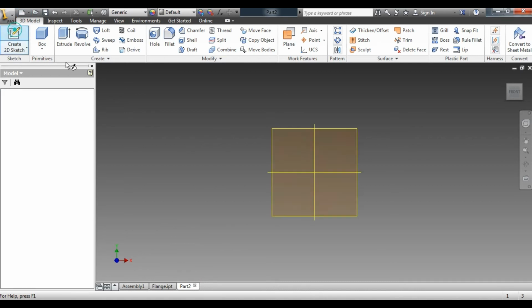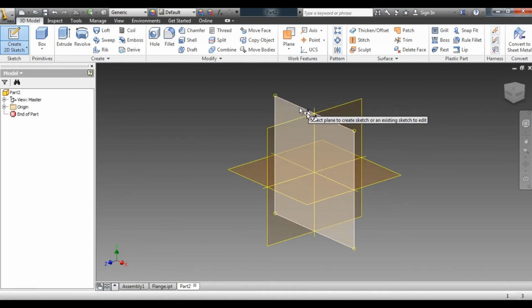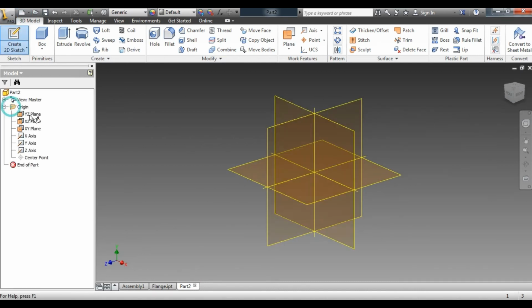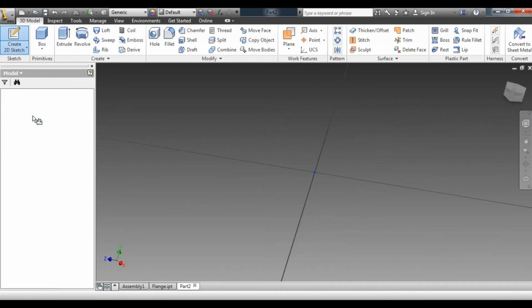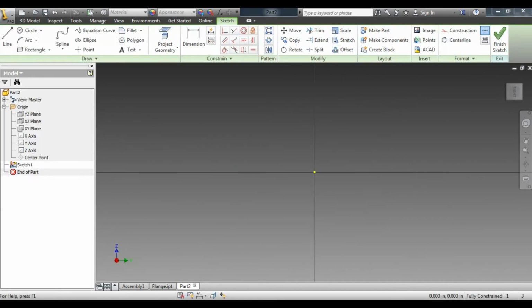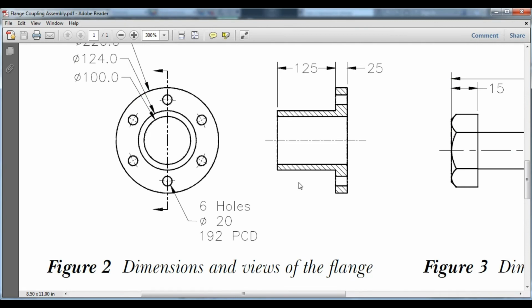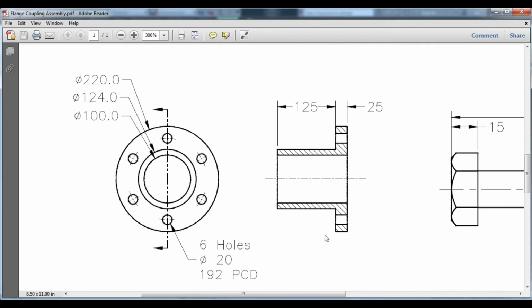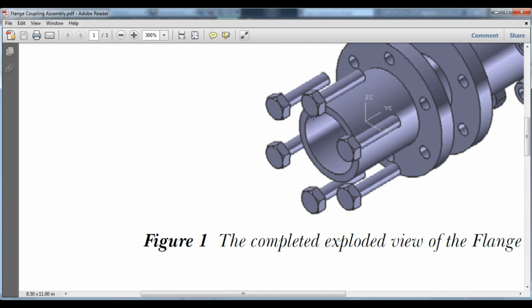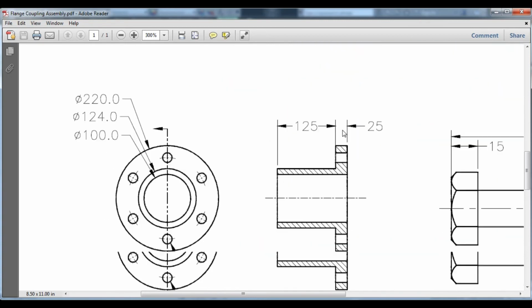So we'll go for a part sketch. I select any one plane from here or from the origin. Here the required items are an axis and a profile. This is the axis around which the profile will be circularly rotated, because it's a cut section. If I cut that, it looks like this.